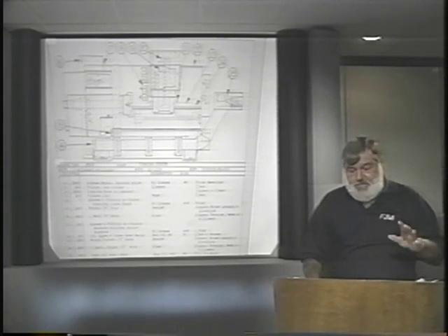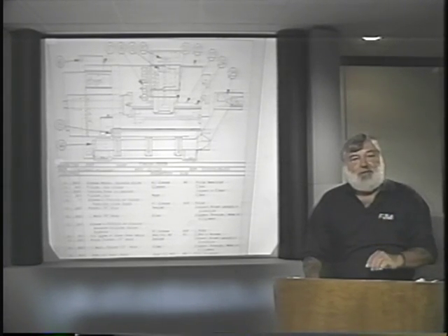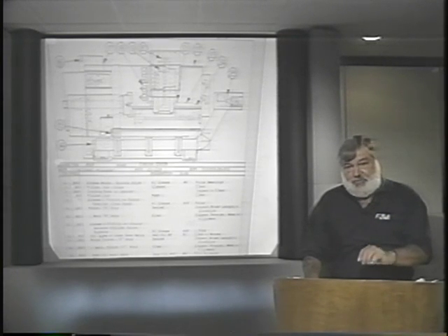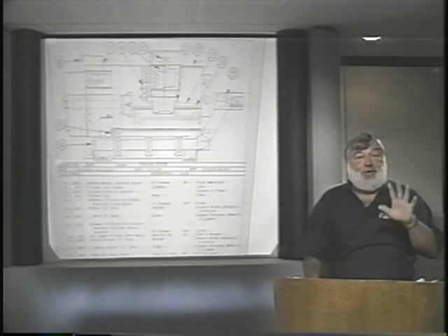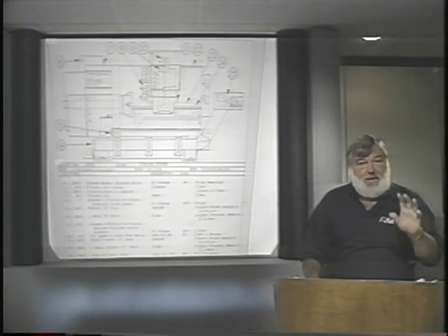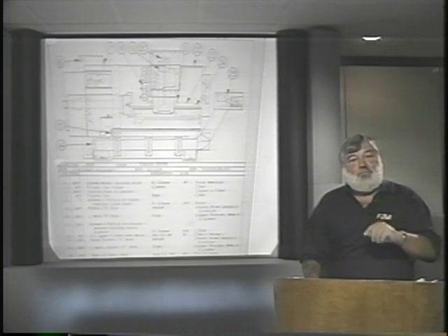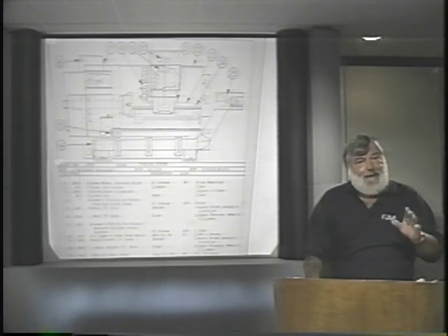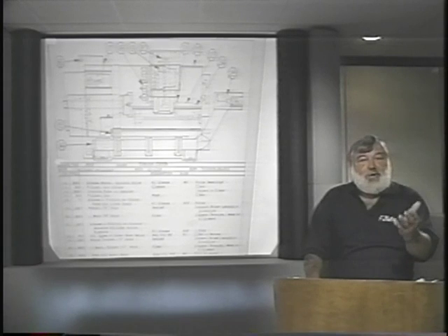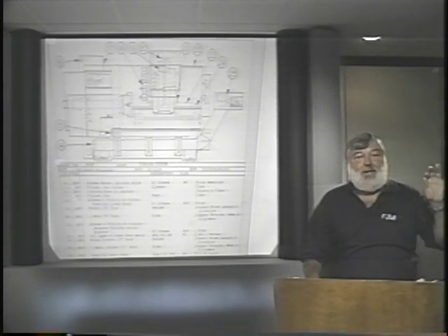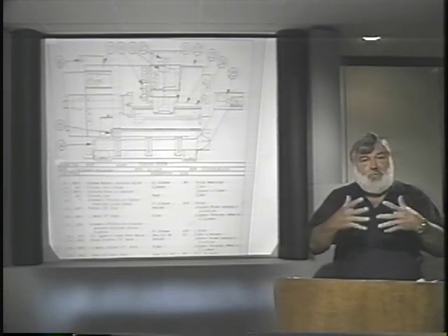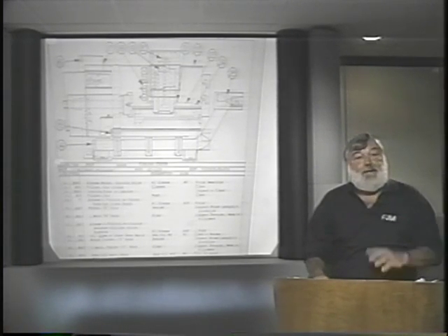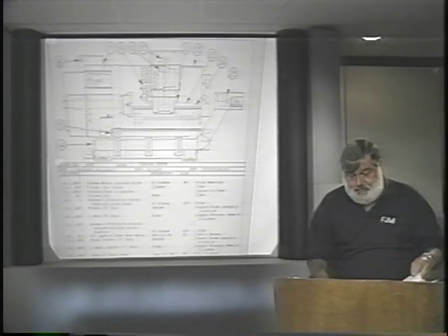If I remember correctly, the lubrication done for this particular application gives the machine operator 10 minutes at the beginning of the shift to do the lubrication process. So again, those 10 minutes are removed from the production planning, capacity planning program. And that's really a key consideration when we start to integrate the machine operators into the PM program.